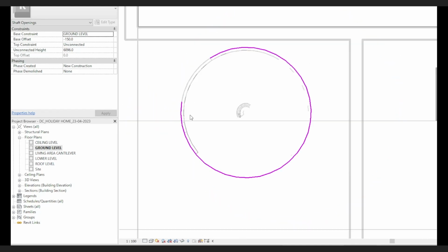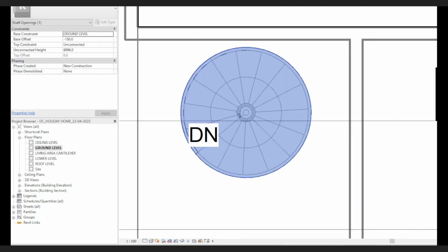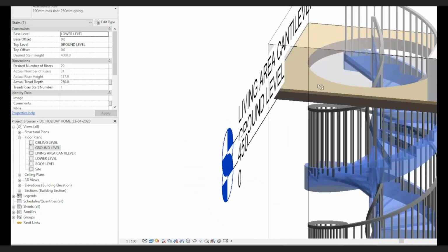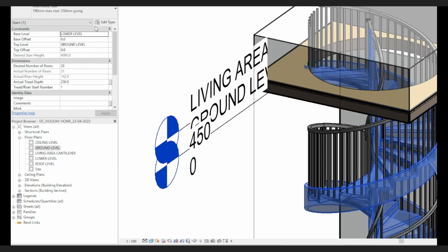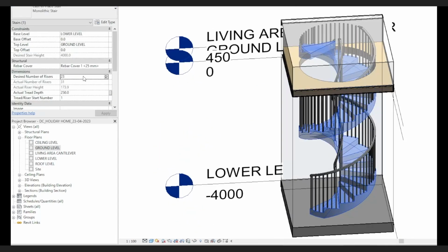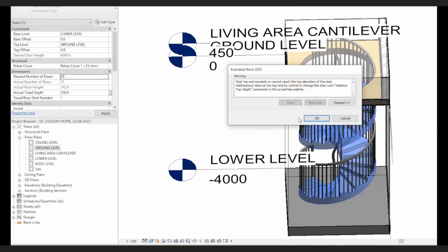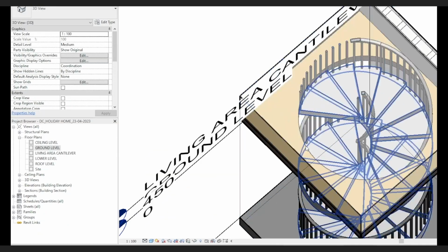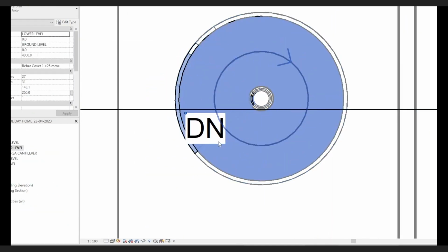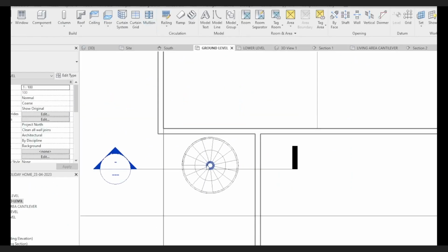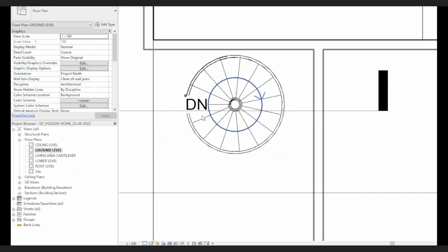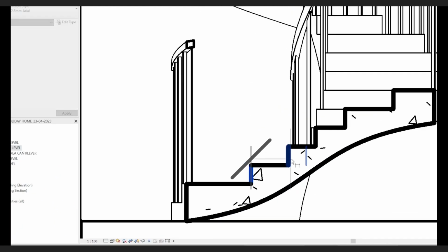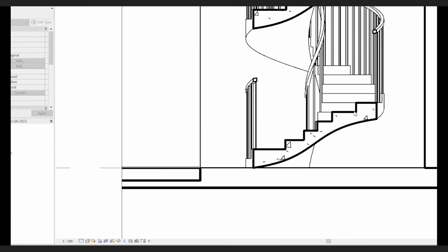So next thing is to create a shaft, a floor shaft that actually cuts through. Normally people would want to cut through the floor, but I discovered using a shaft is actually better, because it cuts cleaner and it doesn't create complications. So that easily works for me. Creating a circular shaft, and yeah, it can fit in the staircase easily. So now this works very well.